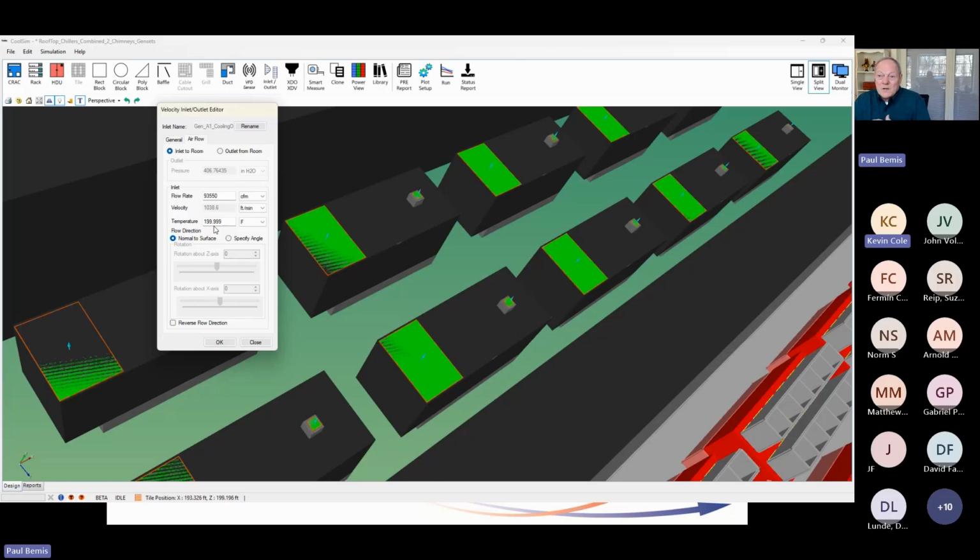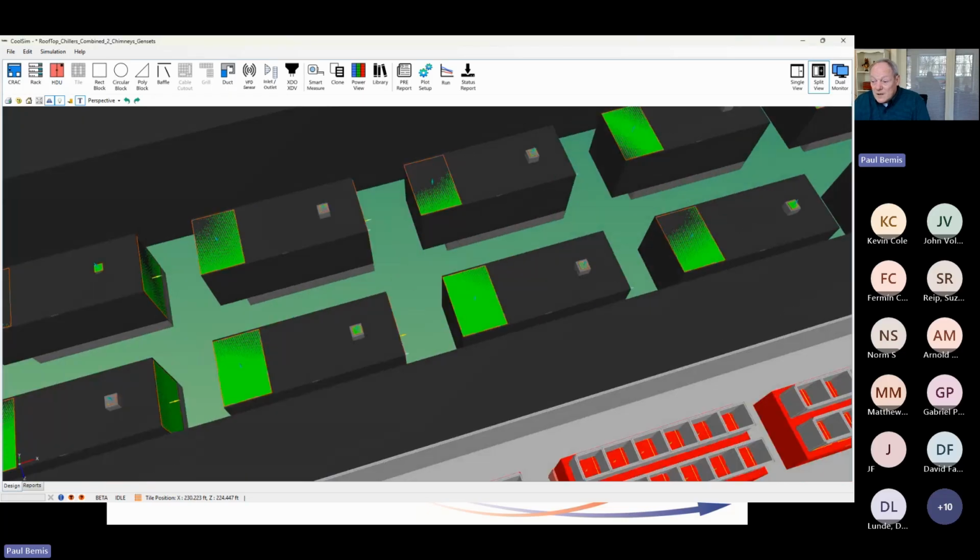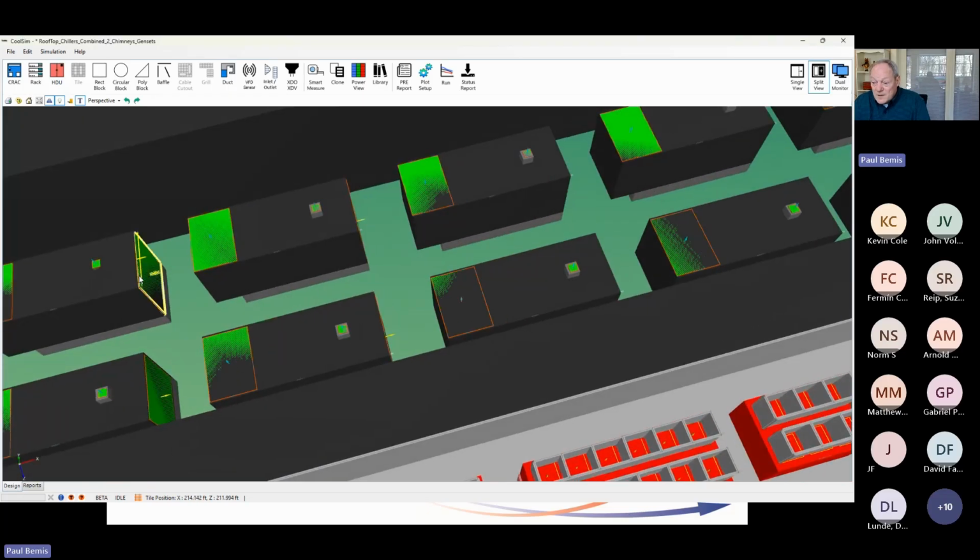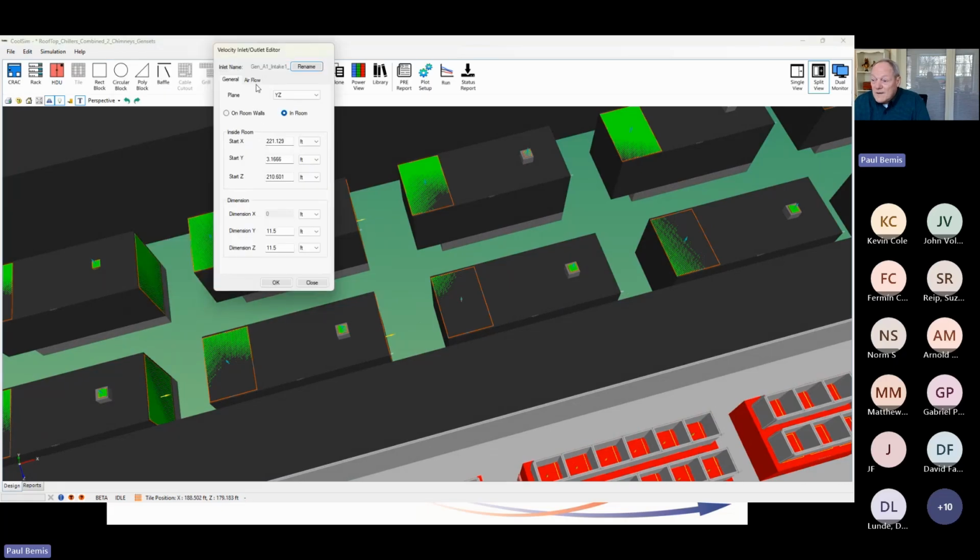They're running, the water jackets run roughly 200 degrees. So yeah, that's what you're dumping at. Mass flow rate, based on the fan they've got in it, is set there. And so you stick that one there. And then the other one, which would be the inlet, you stick on the other side, and this one runs to atmosphere. It doesn't really matter. What you're trying to capture here is simply the amount of air going in.